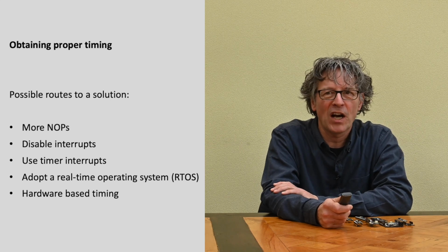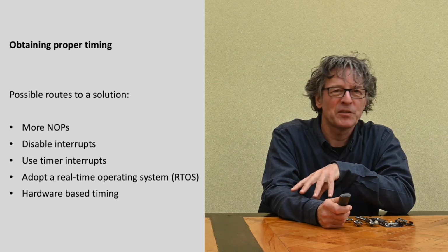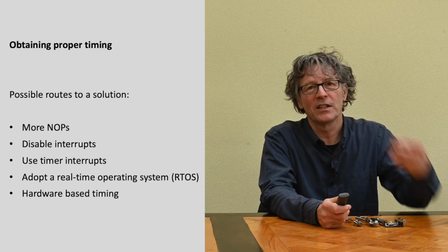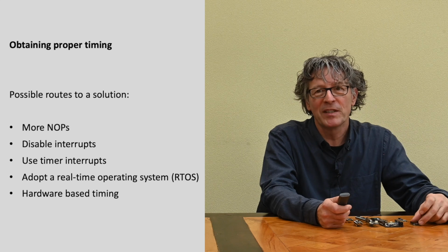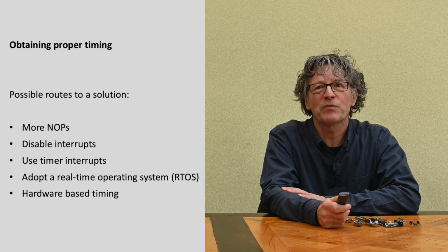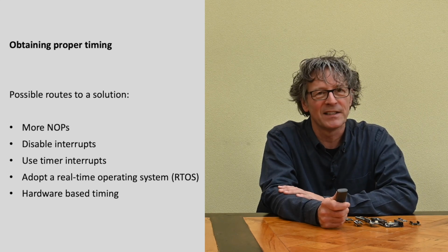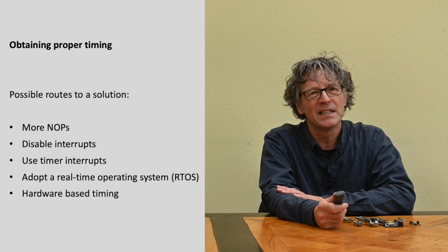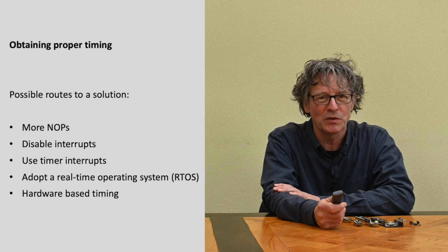The other thing is that these hardware interrupts are completely different per processor platform. So you could completely specialize yourself in doing that for the old Uno type, the AVR platform, the ATmega controller. But then if you would migrate to one of the others, like the ARM chip or the 2040 chips, you have to start from the beginning. You have completely different libraries, completely different interrupt structures, etc. You have to start from scratch, investigate them, see what they can do, how you can use them. So it's not going to be portable across devices anymore at all. So I've not been going down that route.